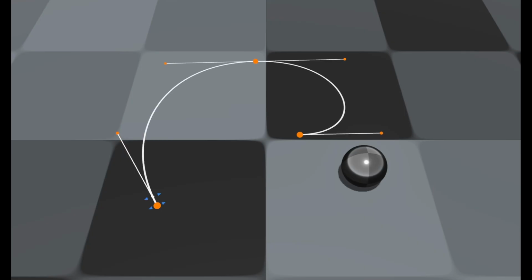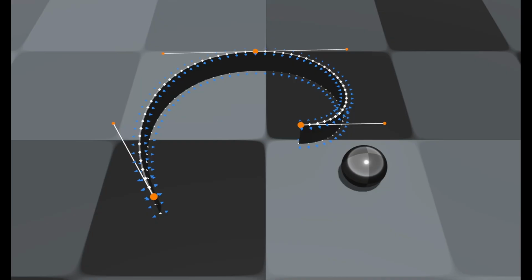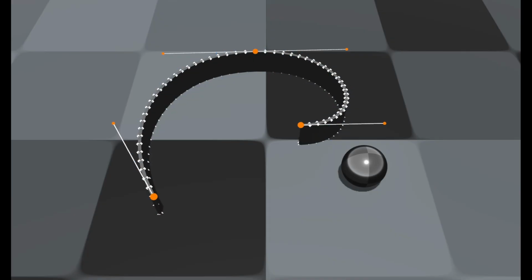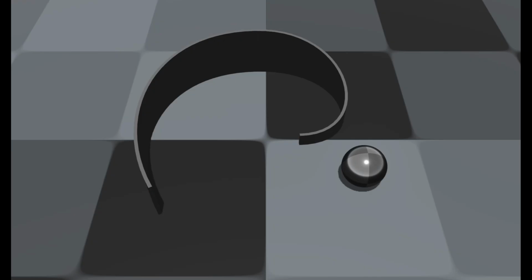Making a typical metal strip guide is quite easy. They can take a path, in this case a Bezier spline, by sampling points along it and keeping track of the normal that would point laterally along the path. By having points get created directly on the path and flat grounded ones, or at least zero elevation in the node space, I could create a variable height ball guide mesh through these points. After that, make more pairs of vertices out of the points using the normal direction before to separate them, and connect them up with the triangle strips. Typically, they should at least be higher than the ball, but I can see potential use for having different heights.